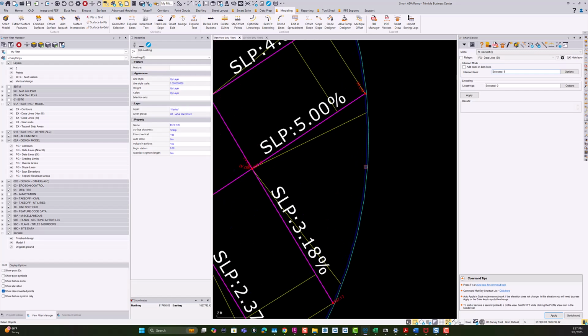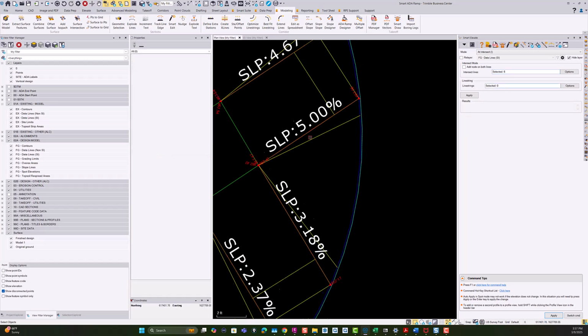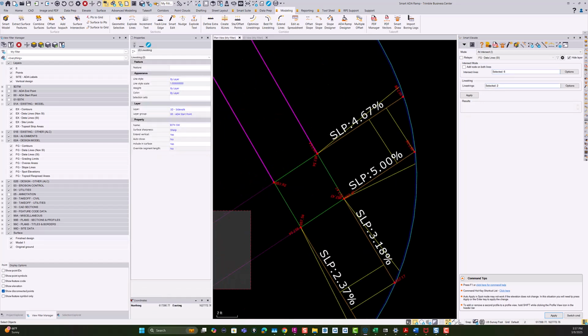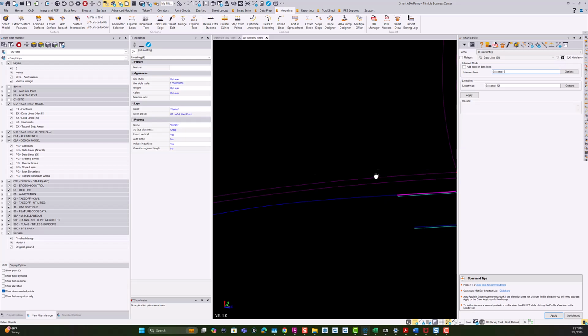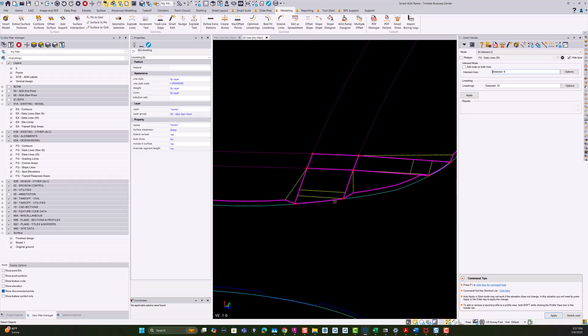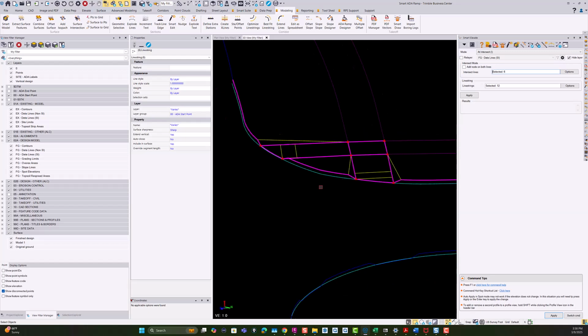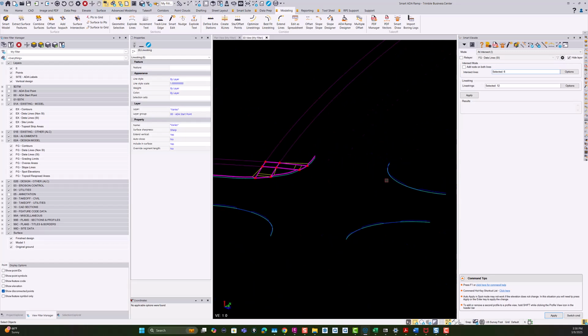and the curb line. And then the lines we want to elevate are the two sidewalk lines where they come to touch the green pad, the yellow lines here around the ramp, and then these crossing lines across the road here, across the ramps there. And once you've done that, I missed one there. So once you've picked the lines you want to elevate, you hit apply, and those will now be elevated. And now if we look at that ramp in 3D, we've got a full 3D intersection calculated out there with all the ramp locations elevated correctly within those tolerances, and then you would move to the next one accordingly.